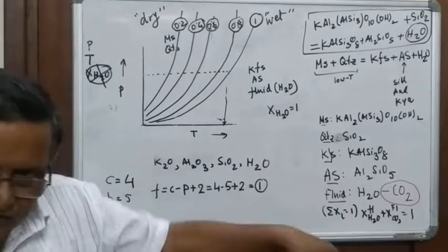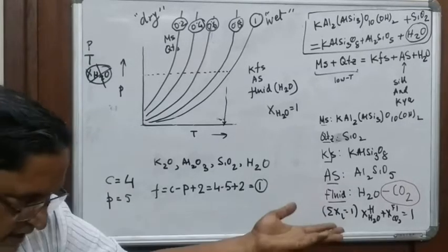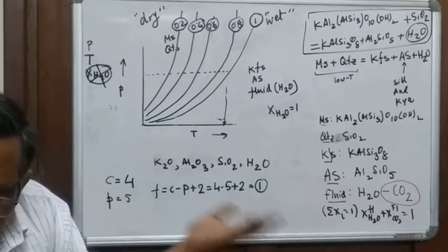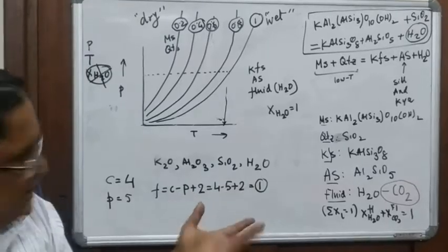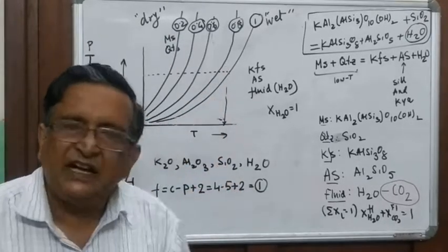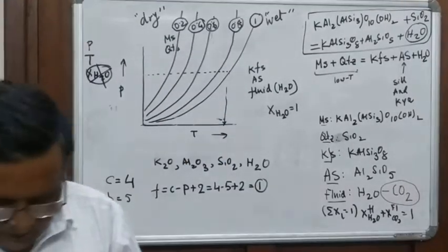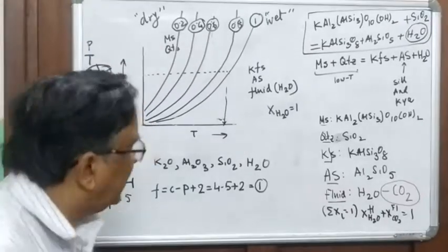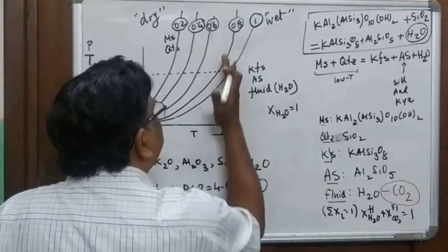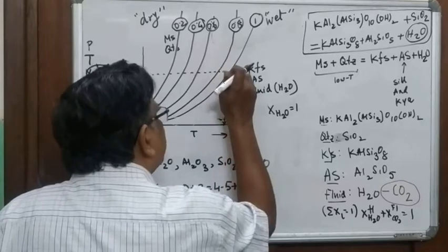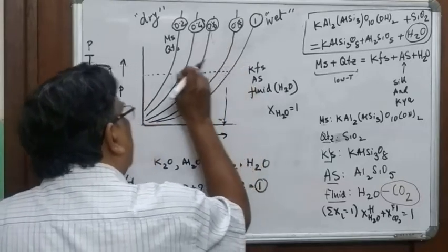You add an equation at the end, and therefore variable minus equation now becomes equal. So variance becomes 0. Of course variance becomes 0 because now you can directly find out temperature. Right? Similarly, you can go the other way. You can take the temperature and it intersects this curve here, and then you get the pressure value.